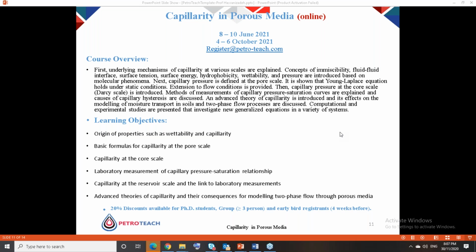If they are miscible for any reason, for example, you have lots of surfactants, then we don't have that much capillarity. But if they are immiscible, there must be capillarity, and that is determined by the curvature of the interfaces between them, as I said, and has nothing to do with the movement, if I understand the question correctly.